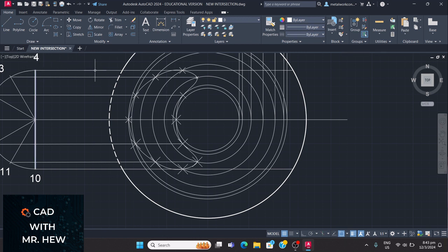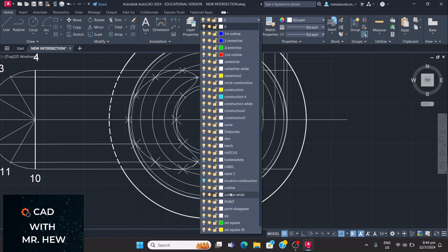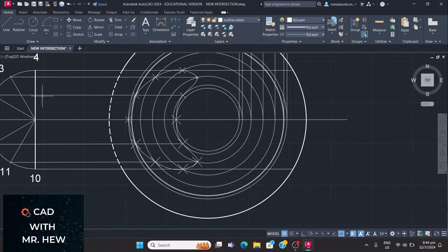Now the cylinder would be right here. Let me draw the cylinder for you. All right, so here's the cylinder now. Line from there to there, and from there to there, right? So everything up beyond these 2 points, 4 and 10, would be dark, and anything below that would be hidden detail lines. All right, so let's draw this thing now.